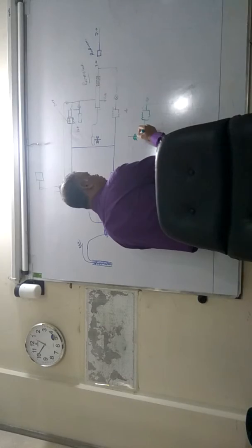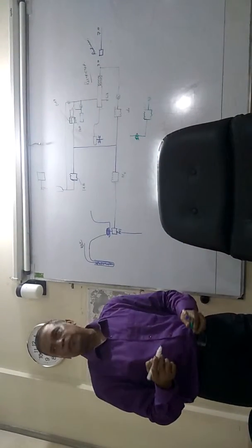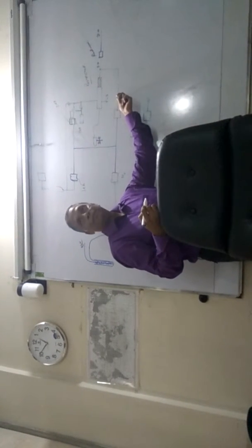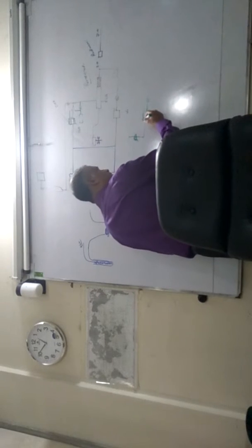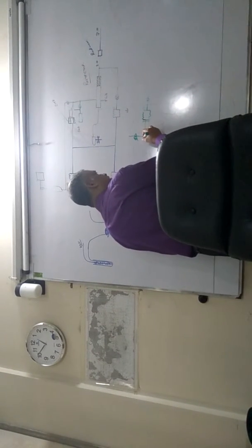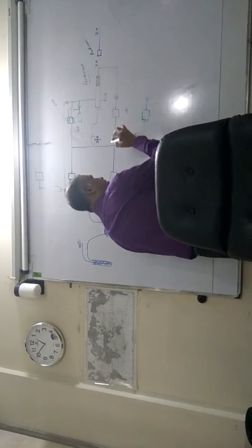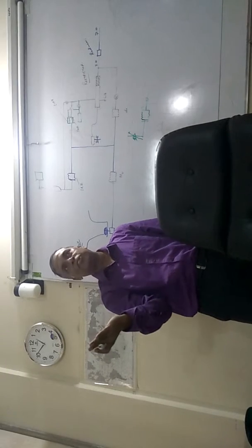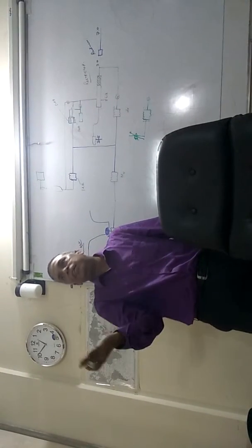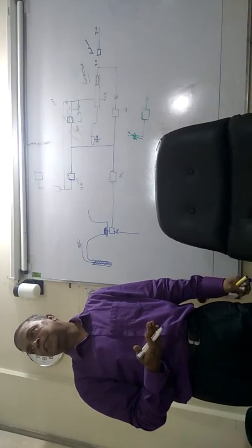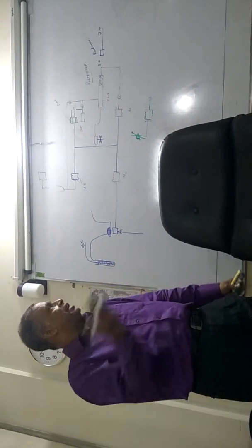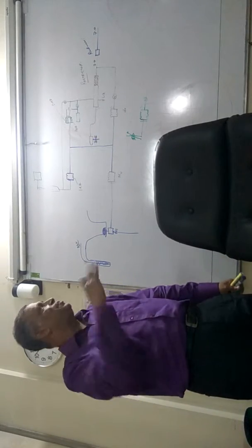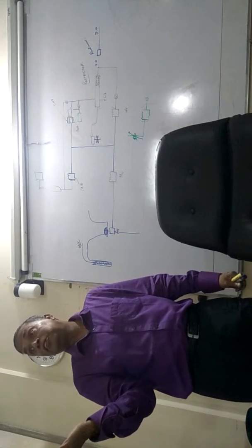So this is a kind of fulcrum, and you increase the pressure in this bellow by operating this valve. So what happens? This expands to about this point. So this end goes here, and it takes a new temperature range. So when pressure is increased or decreased, it will reflect on a dial, isn't it? Exactly, that is what is happening here. Yes, the red dial is attached to that bellow, with a fulcrum in between. So pressure increase means the temperature shows an increase on the scale.